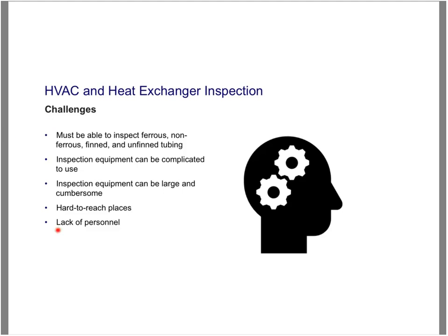Another problem is a lack of personnel. Not many people actually do tube testing. It's an eddy current technology, so being a licensed eddy current level 2 or 3, there's not many of them, at least in Canada, there's not many of them. So we like to try and find a way that we can get more people into tube testing quicker.